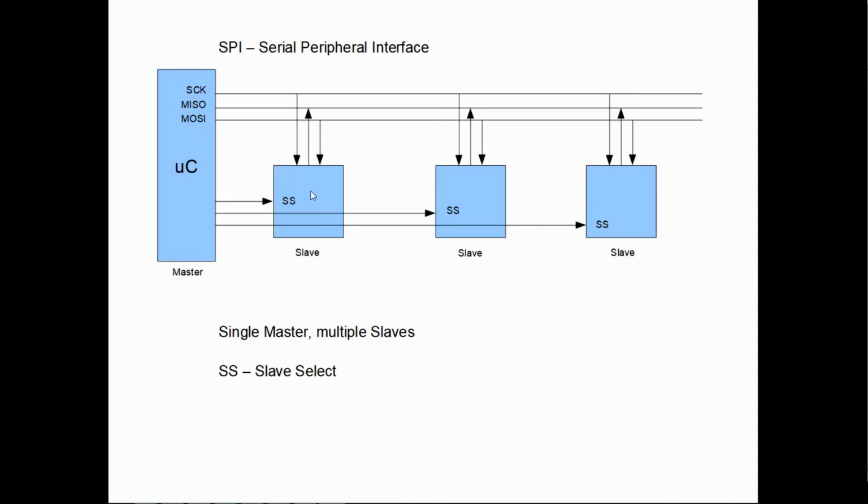Now just thinking about it here, I realize that you can't really have more than one slave going on at the same time because it's clocking data out. And if you've got 2 slaves clocking out different data, there's going to be a contention on the master in slave out line. There are situations where your slave devices are one direction, like this display here. I can't read from the display and I can only write to it. And so I don't have the master in slave out line connected up.